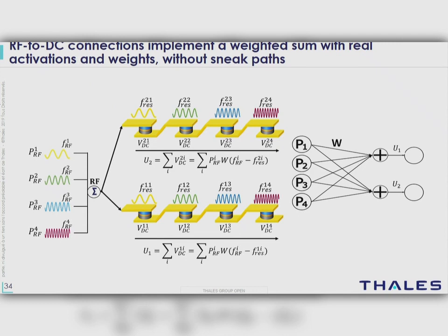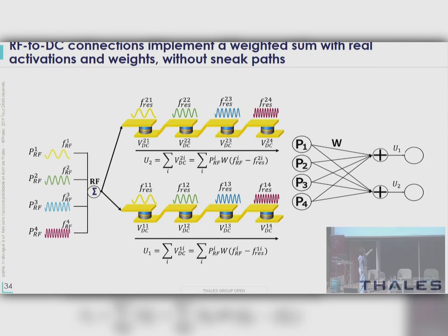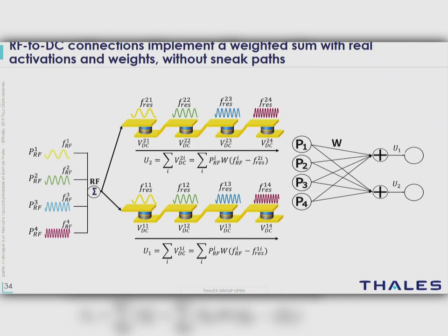And we think that this frequency multiplexing technique really helps you improve the connectivity. Because you see, as I told you, you take all the signals from one layer and you send them to all synapses. And you see these are separate chains. So you might have some inaccuracies that come from things going on in one chain, and we can discuss this later. But you will not have issues going from one chain to another. This means that you don't have inaccuracies going from one output neuron to another output neuron. While when you have these crossbar arrays of memory devices, this is something that you do get with sneak paths, for those who are familiar with it. We can discuss more about this later. But we think that this really simplifies the architecture to go to higher connectivity.